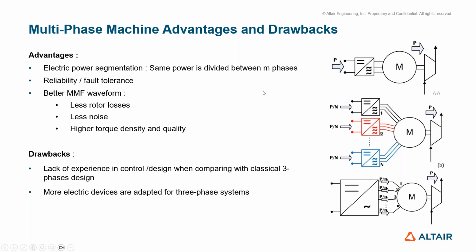So it gives a better reliability of the machine, and especially it helps in designing power electronics because less power is in play in those types of machines. Also, the more phases you have, the better the fault tolerance of your machine, because if one phase gets broken, you have more phases that will take the lead from it, and you will have better reliability.